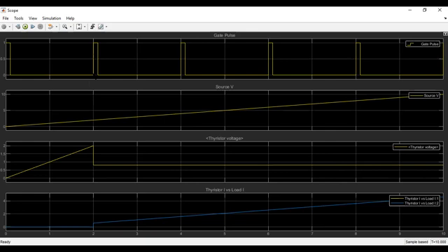When the first pulse flows through, the junction 2 breaks, and after that, whatever the number of pulses given, whatever the gate current is given, no change occurs. The function of the input pulse is just to break the junction, nothing else. Once junction 2 is broken, the current will flow normally like this.